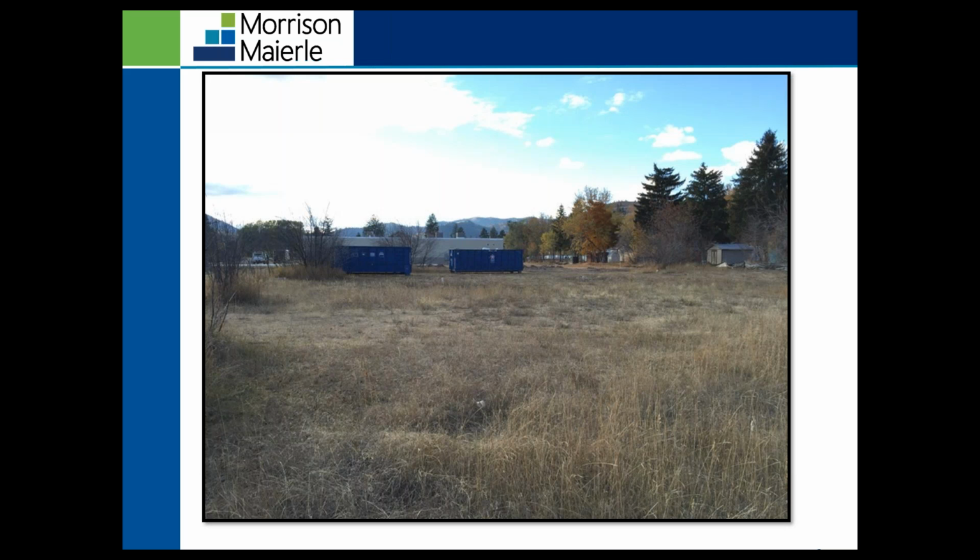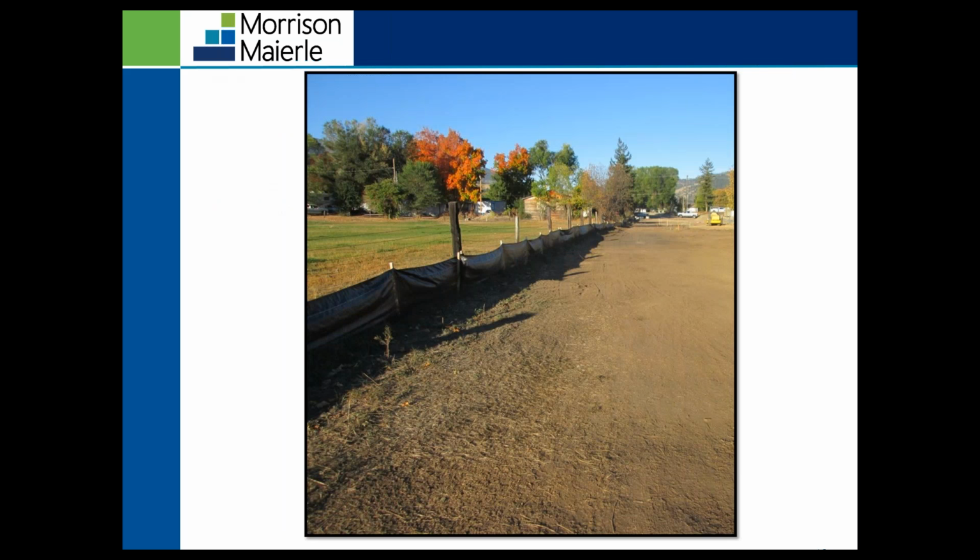So like I said, that's an erosion control BMP. An example of a sediment control BMP is a silt fence. This BMP is designed to intercept and slow sediment-laden sheet flow. It allows for sediment to settle before the stormwater discharges from the site. So it'll catch any sediment that the stormwater is carrying, and then allow the sediment to settle before the stormwater discharges.